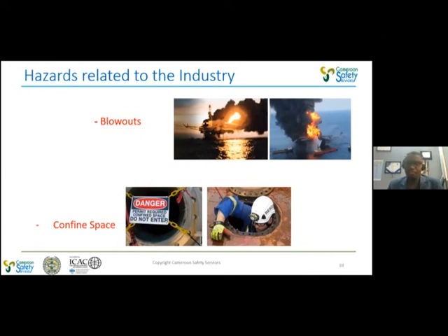or some activities that might require entering confined space, such as going to weld maybe a hole in the confined space, and then later on the gas from the welding accumulates, exposing you to oxygen deficiency, and then suffocating you.